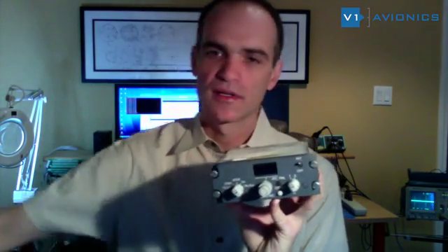So all these pins you see back here have an output that produces a signal, an ARINC 429 compatible signal, that can be interfaced with the flight simulator. The same holds true for other well sought after devices such as altimeters, like this guy here, or radio heads, like this ATC radio right here, that is ARINC 429 compatible, or this radio head right here. So let's go to the workbench and let me show you how this ARINC 429 interface works and how it can be interfaced with your flight simulation software.